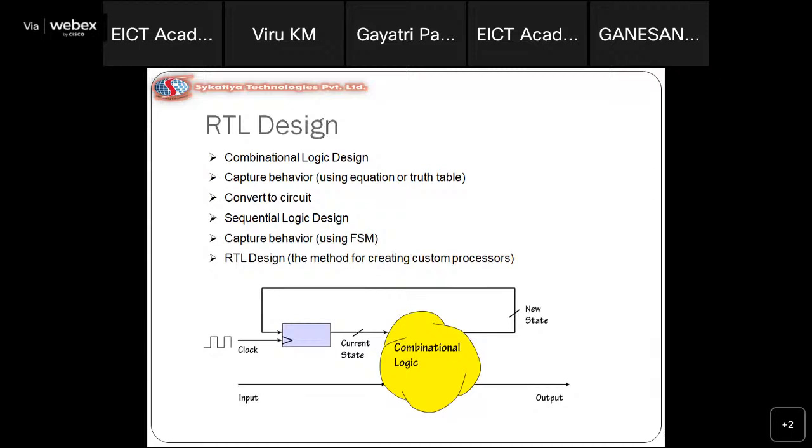You have to do it for the particular hardware model, so you have to use a particular tool. If I am using a Xilinx FPGA board, you have to use the Xilinx ISE or Vivado tool to download to the FPGAs. If you are using Altera, you cannot use the Xilinx ISE tool. In Linux you can do it, but on Windows it's not possible. Understood: if the hardware is Xilinx, you have to use Vivado or ISE, and for Altera you have to use the Quartus tool only. Then you can download to the FPGAs.